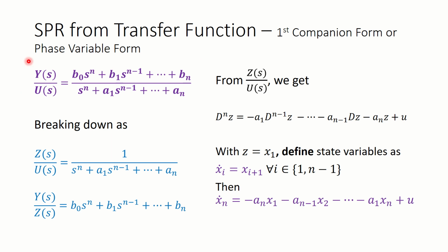So one may ask to derive the phase variable form, then you cannot derive any other form. That is also something one needs to understand, and we also discussed it slightly in the last lecture, that we can derive another state space realization from the same system. State space realizations are not unique, even though the system is unique, even though the transfer function is unique.